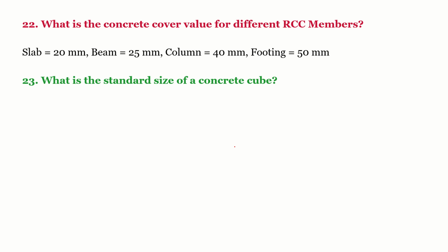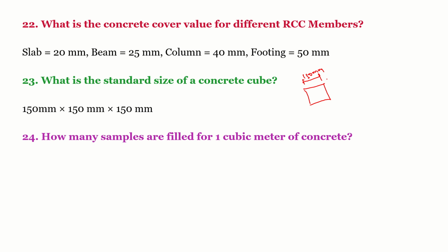Next is, what is the standard size of a concrete cube? Just now we have seen concrete strength is based on the cube. The cube dimensions are 150 mm by 150 mm by 150 mm, that is 15 centimeters.